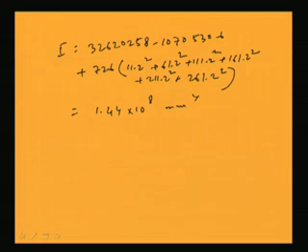Now, it is easy to find out the sigma Tf. Sigma Tf calculated means tensile stress due to bending, right. That will be basically M by I into y.